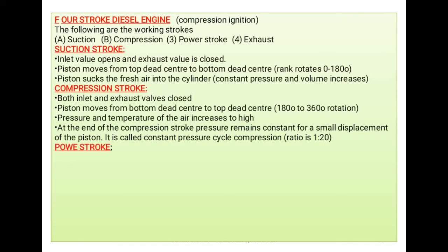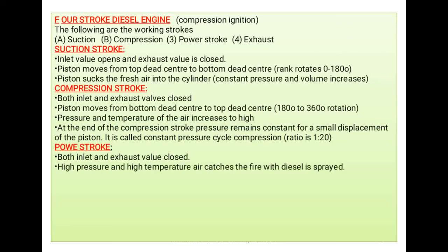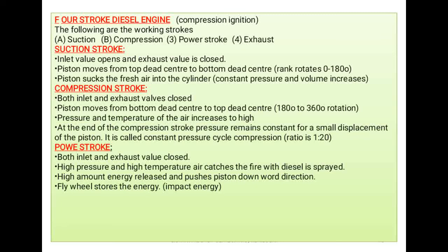Power stroke: both inlet and outlet valves are closed. The high pressure and high temperature air ignites the diesel fuel sprayed by the fuel injector. Due to that combustion, a high amount of energy is released that pushes the piston downward. The flywheel stores the energy. The high-energy gases move the piston downward from TDC to BDC and create the power, and that energy is stored by the flywheel.